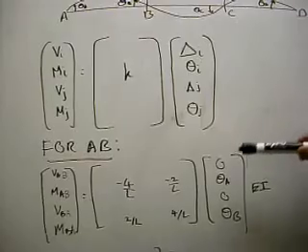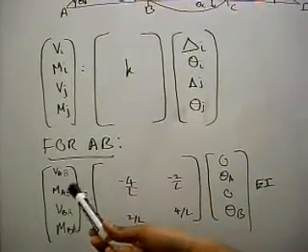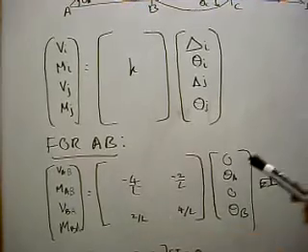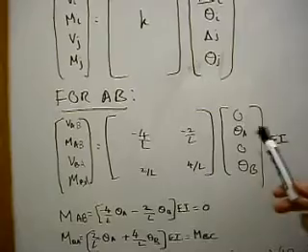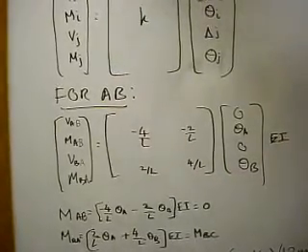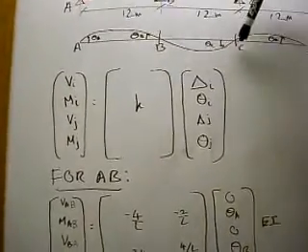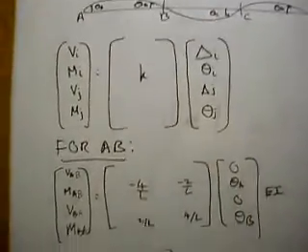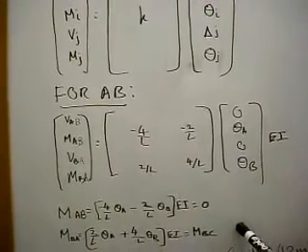We have deflections at A and B equal to 0, and we're concerned with moments at A and B and the rotations at A and B. So writing the whole matrix down, we get these equations, and since the moments MBA and MBC are going to be equal, we have to equate these two equations, which we do later.